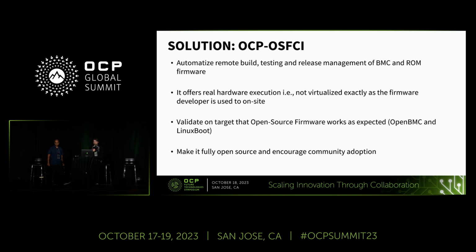workflow. So we started to work on building Docker images which were able to build a firmware image. We start from GitHub, and we pull the source tree. We build this source tree. If the build fails, the error is reported to the end user. If it is a success, we deliver a firmware package, which can be a BMC image, a ROM, or a BIOS image. That image can be loaded directly to the tool and to our target systems and can be tested. Everything can be done manually within the tool, but remotely, or can be fully automated either through the web UI or through the API that we have integrated into it.